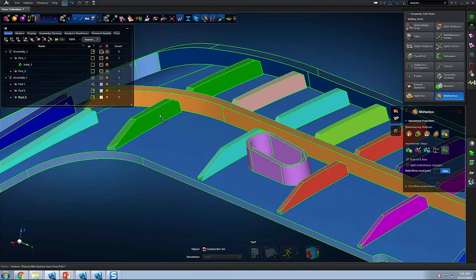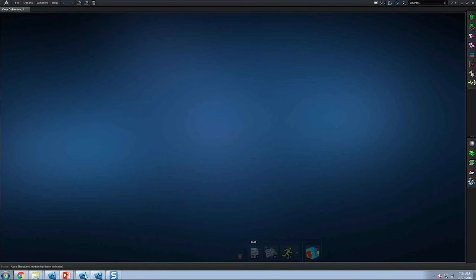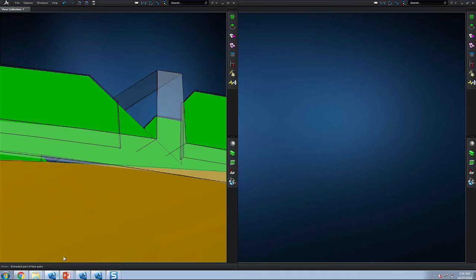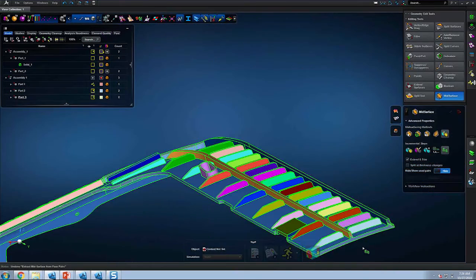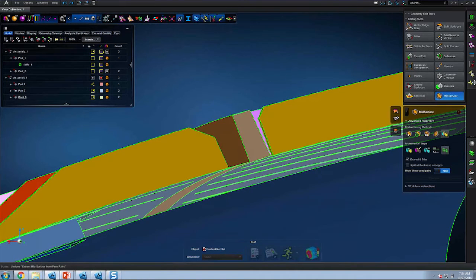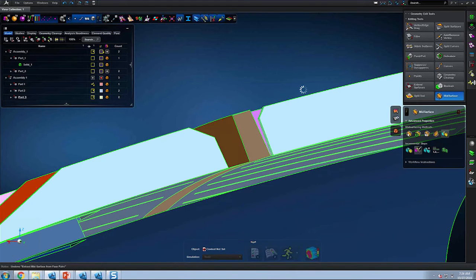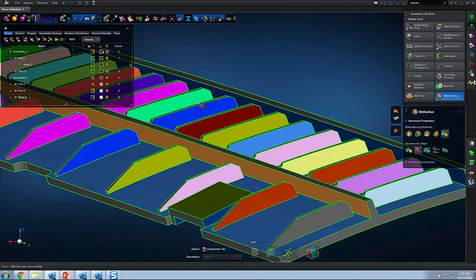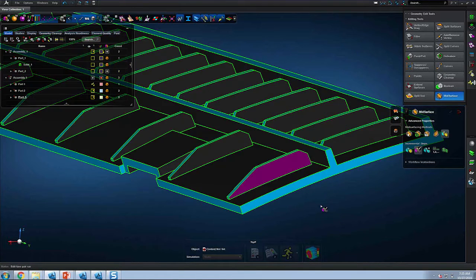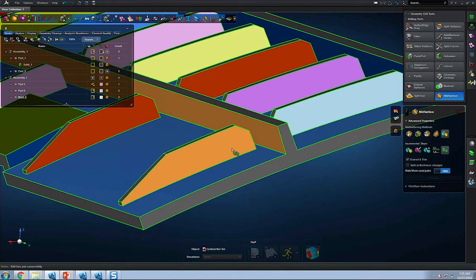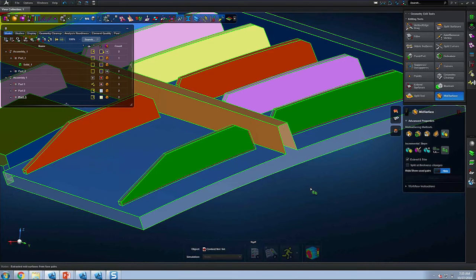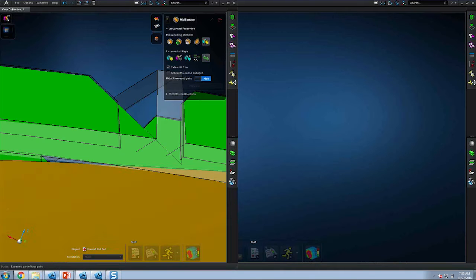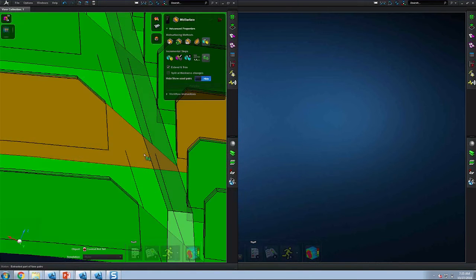Again, these ribs were originally connected, as you see here in this example. What I want to do now is remedy this. The reason we have this issue is these pairs are the same pair. What I can do now is deselect these pairs from every other face that you see here. So now when I create my extraction here, you'll find I get two individual pieces, whereas before I was getting this connected midsurface for these other pairs.